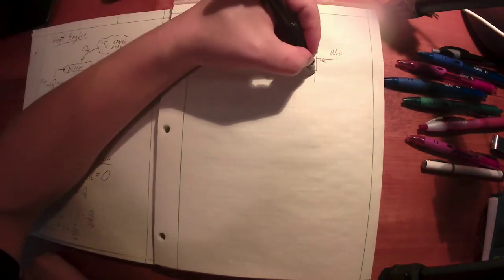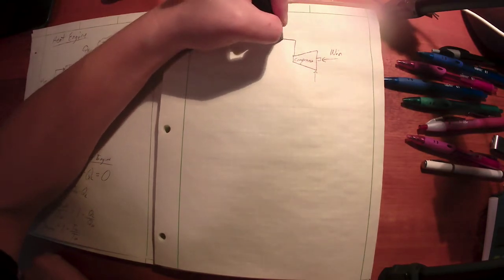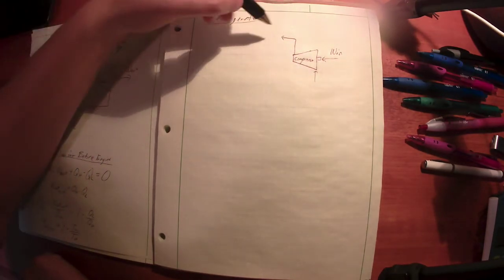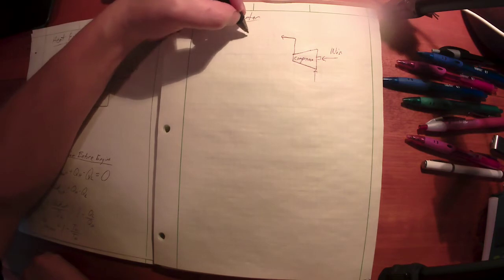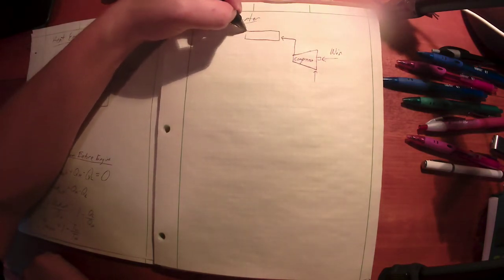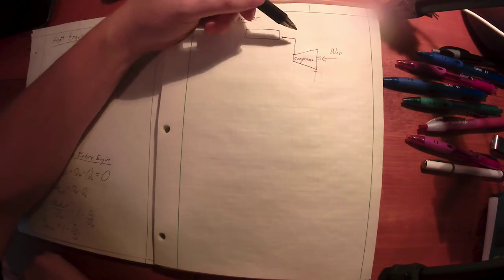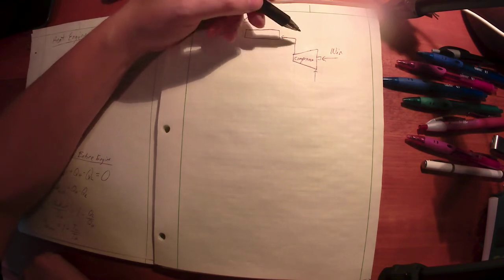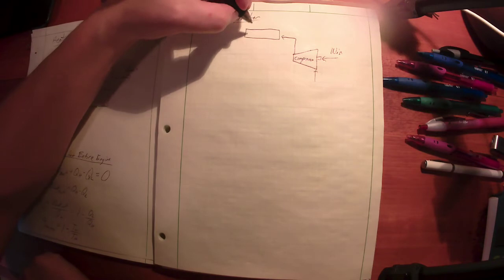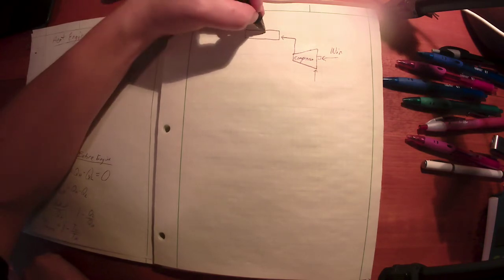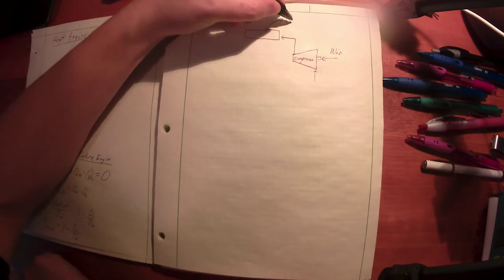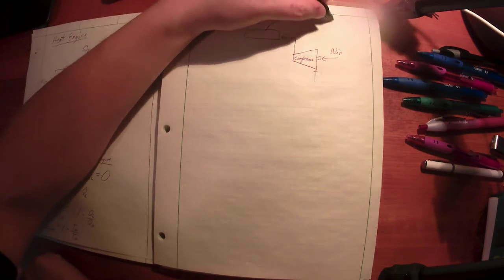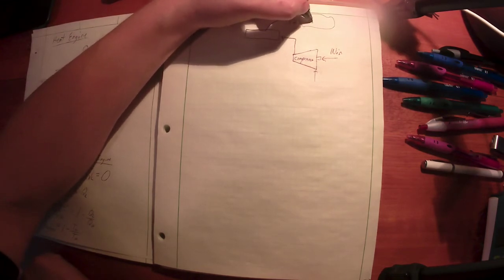So I'm going to have mass coming in, and I'm going to have mass going out. The whole goal of a compressor in a refrigeration unit is I'm going to have vapor coming in, and I'm going to increase the pressure and the temperature of that vapor by squeezing it and adding energy to it. And I get it so hot that it will actually now lose heat to the high temperature body.